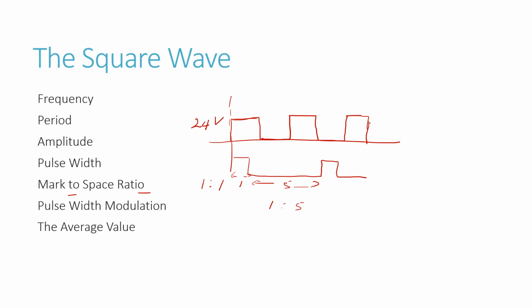So frequency is discussed in the same way as for the sine wave, right? The frequency is how many complete cycles. A complete cycle here will be from this starting point back to a similar point. Here we were going up, so we can't say this is a similar point. The other similar point will be here, where we're also going up, right? So the question is, how many of these complete cycles from here to here do we get in 1 second? That will give us the frequency: the number of cycles per second.